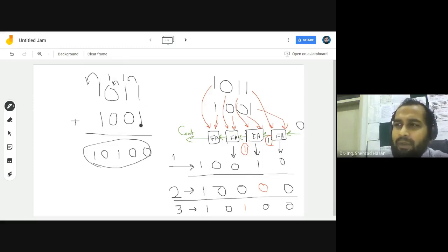But if I had a bigger adder, and I break that into blocks, then you're going to see that if the carry input to that block is known ahead of time, then we can obviously go to that step immediately, right? So what happened in the second step was because of this full adder which has produced the result after the second step.